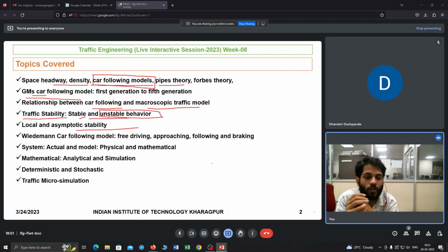Suppose you want to know what distribution it follows along an urban corridor, along an urban stretch. If you are using macroscopic parameters, which only have three parameters, speed, flow and density of a traffic stream, we do not know the individual vehicles, so we do not know the interaction, so we do not know the time headways. So it is not possible at all to calculate those things without using traffic micro simulation models, right? That was one example of the purposes or occasions in which you want to use traffic micro simulation models.